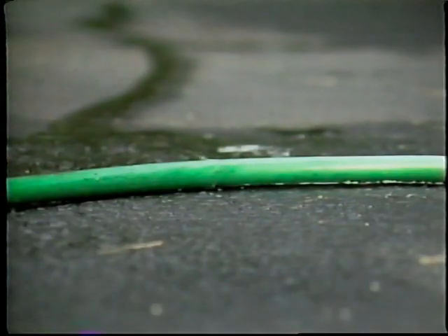While other factors, such as the length of the restriction and the pressure on each side of the orifice, will affect the flow rate, the variable most often used to control flow rate is the diameter of the hole, or its cross-sectional area. A good example showing this relationship is a leaky garden hose.